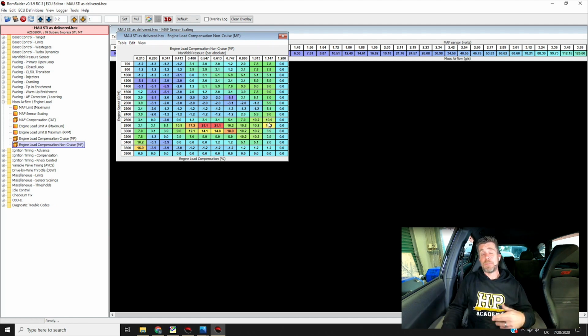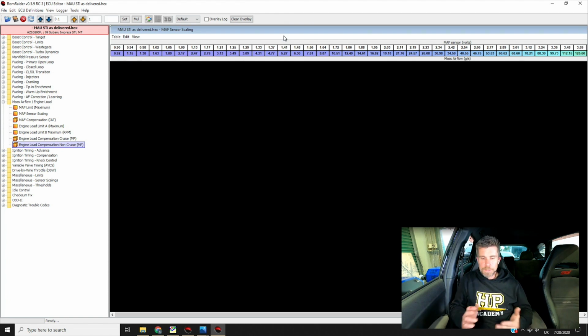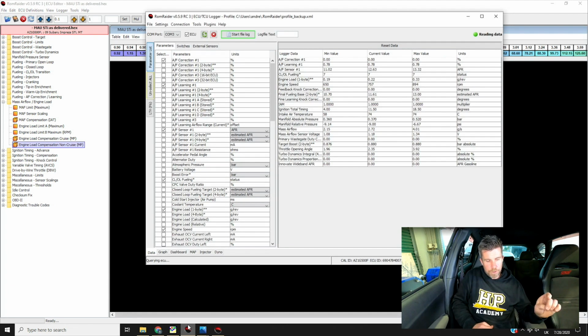Interestingly as well, in the aftermarket there are fixes for the mechanical issue. In particular, Cobb deliver a full fuel system upgrade, and if you go with that, it reduces or eliminates that problem with the fuel pressure pulsations. You can essentially zero that table out and concentrate on your MAF scaling. So what this brings us to, and why I'm going on about this, is that in the Subaru tuning world we're in a unique position where, despite the fact that the scheduling for fuel and ignition is primarily off mass airflow, we actually do need to scale that load compensation table as well. So we need to keep that in mind, which we're going to have a look at how that works as we go in a little bit further.